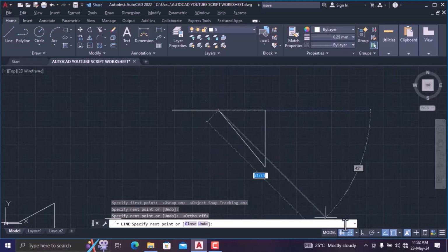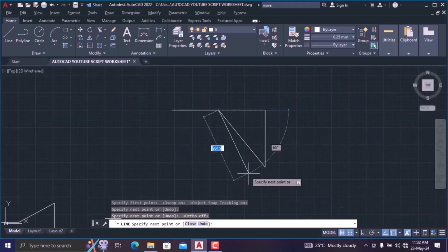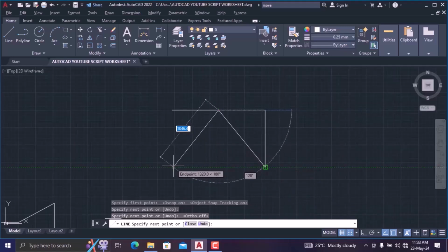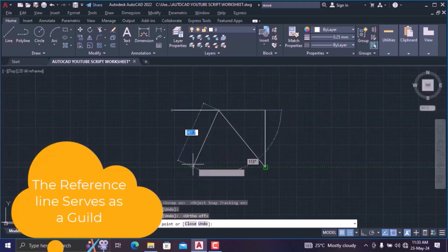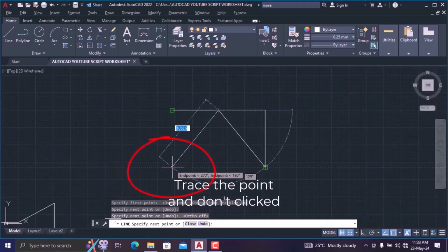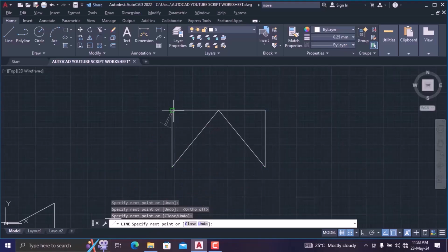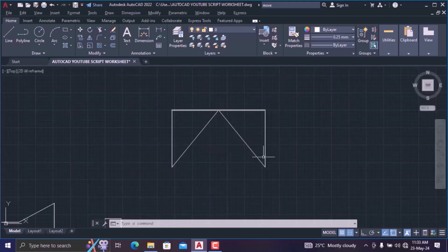Now I also need to turn on my 3D tracking. Notice what this does. When I drag down to this place, I can take reference lines from here. I want to join it with this, so I can also take reference lines from here. Notice how it joins, and it gives me a point where I could click, and I could also join to this endpoint. Now this object snapping tracks the important points in the line, the end point, the midpoint, and so on. So that's how we could join points in lines.